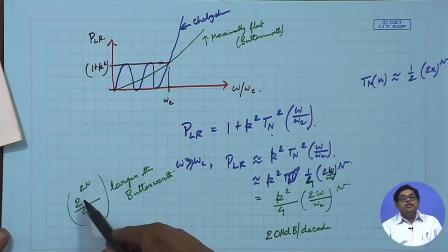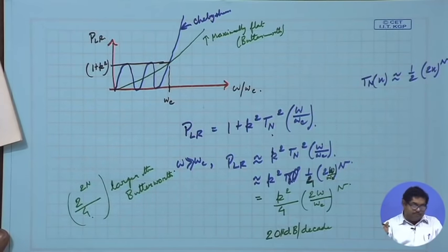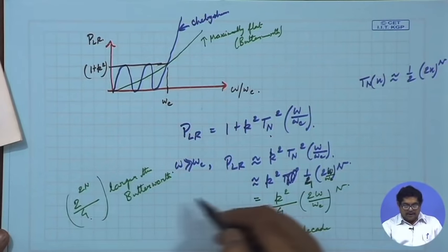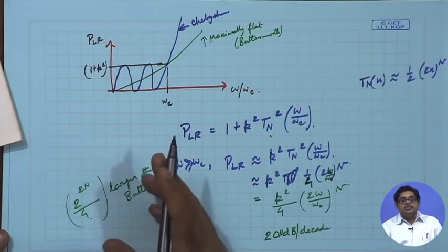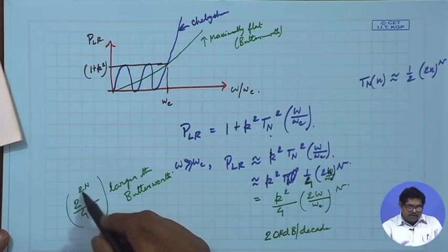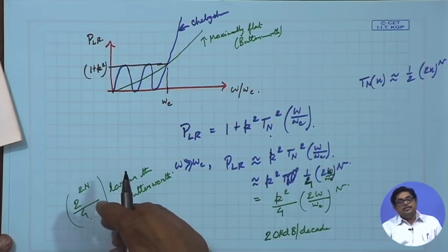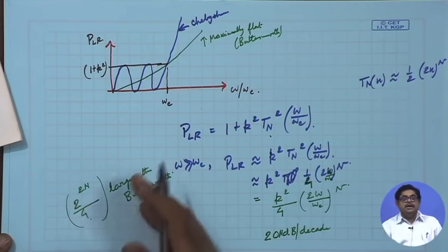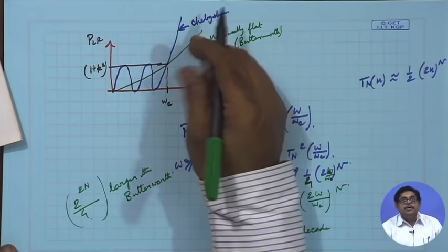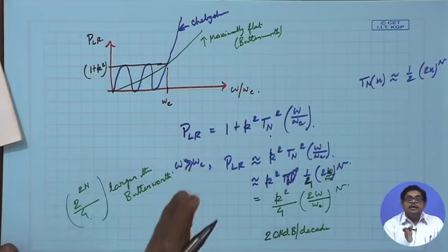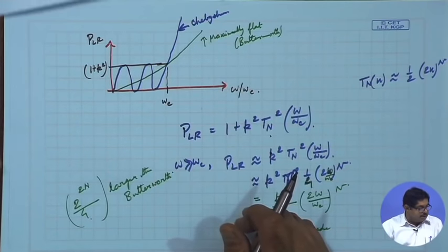Now, obviously, if you go for n equal to 1, that means a single-section Chebyshev, then you do not have any advantage. But the moment you go for n equal to 2 or n equal to 3, etc. So, n equal to 2 means you have 2 to the power 4, 16 by 4, that means 4 times larger than Butterworth, always you will have the value. So, even if the slopes are not much different, you are getting more value of insertion loss. So, your alpha is increased.